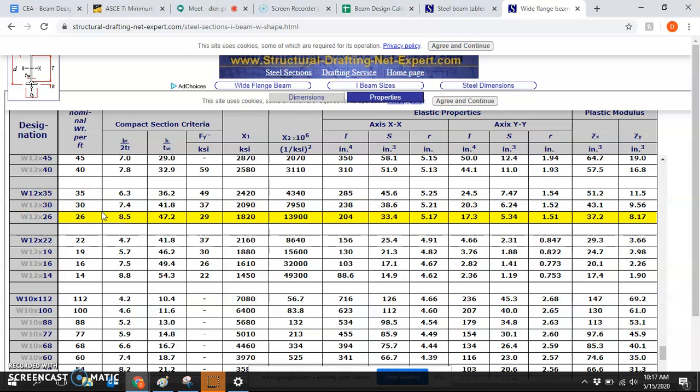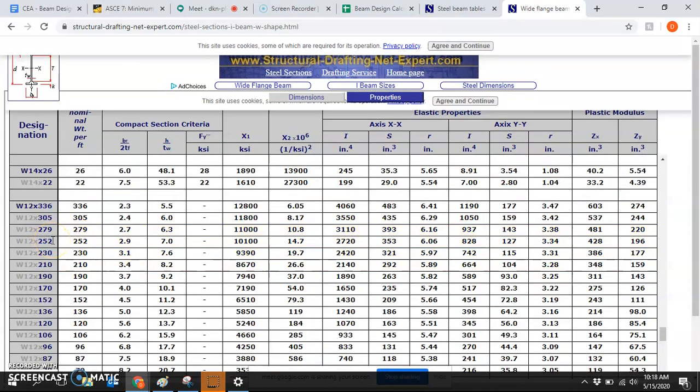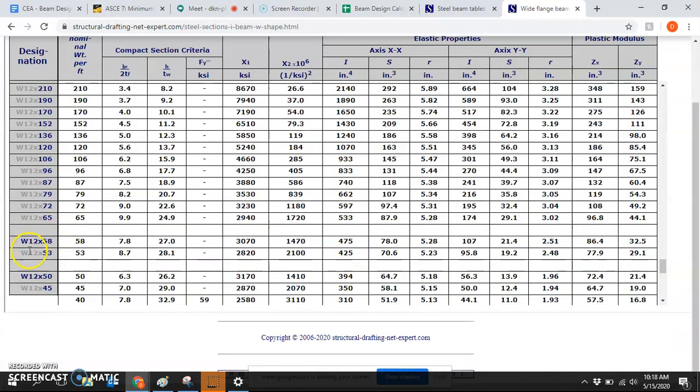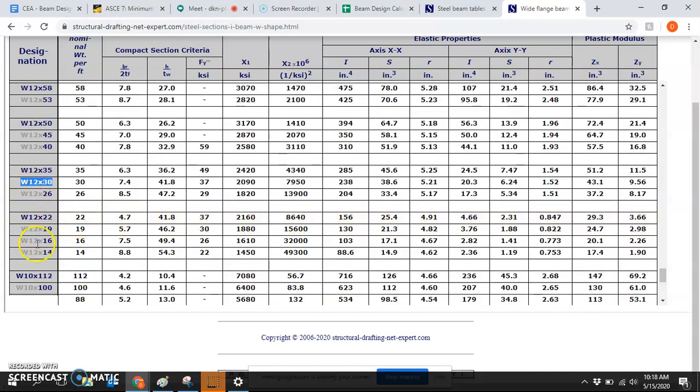Typically, as a rule of thumb, the member that works is the one that's closest to the lightest member for that entire W series. So if you're picking like a W12x252, there's guaranteed to be one that's lighter. You want to get as close to the bottom of the W series as you can. Does that make sense? You want to be closer to the lightest member that exists for it. If not, you can probably get the next tallest one.